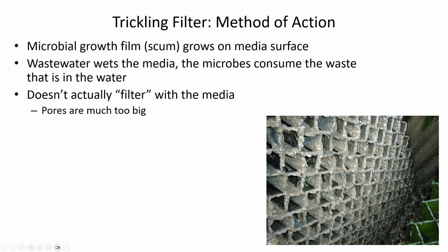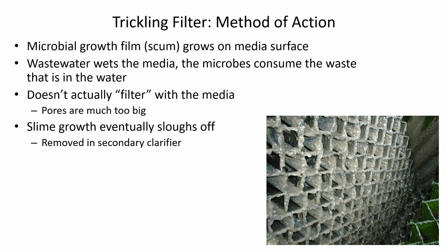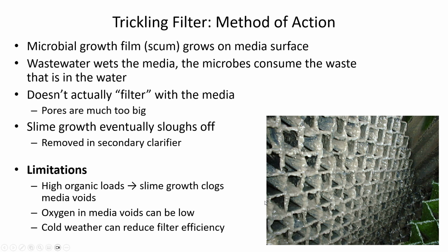The pores are much too big. What we're having is just some scum accumulate, and then eventually the scum layer gets too thick, sloughs off, and it can settle in the secondary clarifier. So we're turning dissolved BOD into something that will physically settle. And this slime, once it sloughs off, will physically settle.